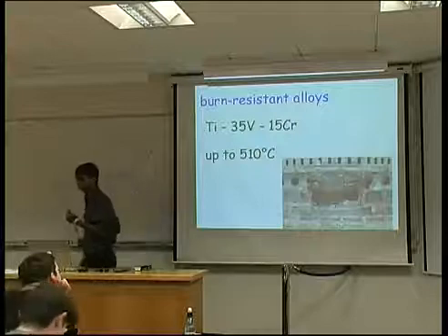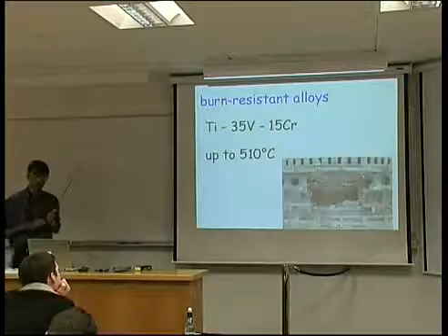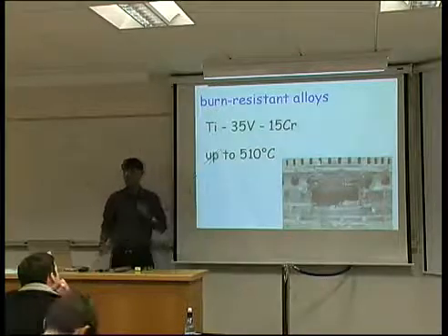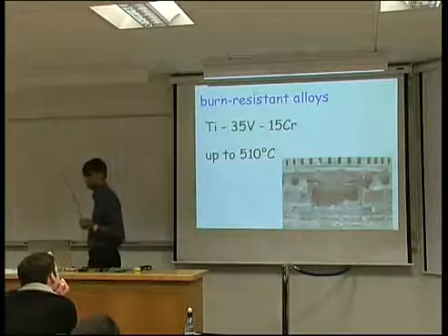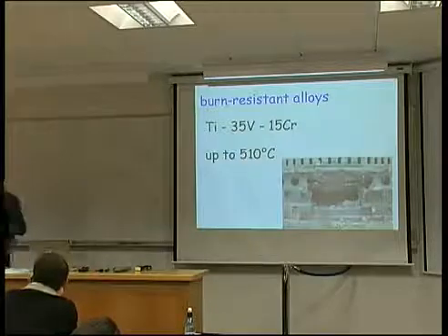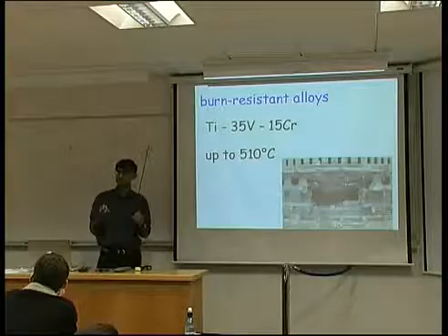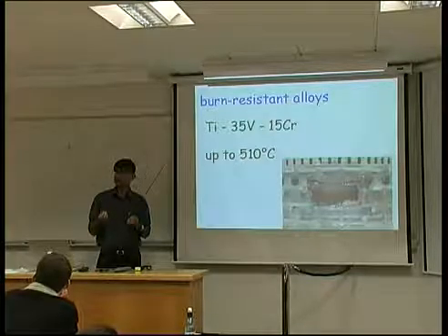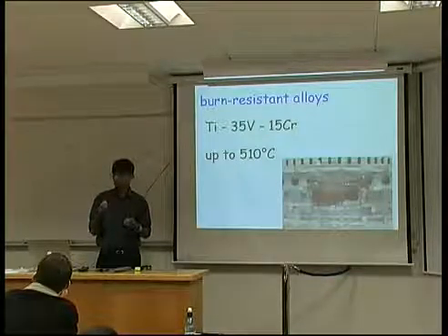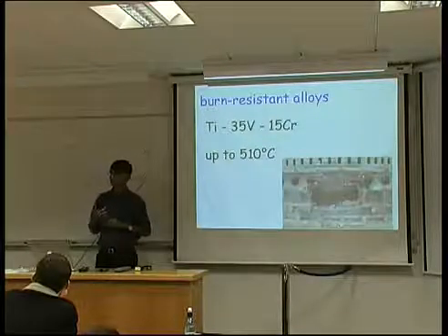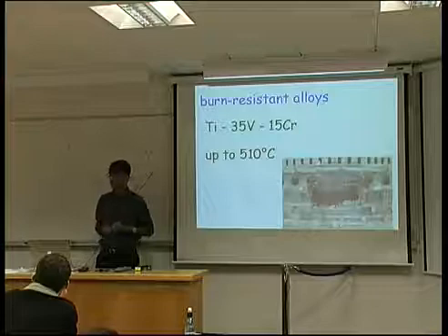And there is another system which has been invented in Birmingham University. This alloy suffers from brittleness. Okay? There's another system which has been invented in Birmingham University, again based on chromium additions, but with certain impurities, very carefully controlled, so that you get a very high ductility. And that probably is going to have an impact on engine design in the near future.